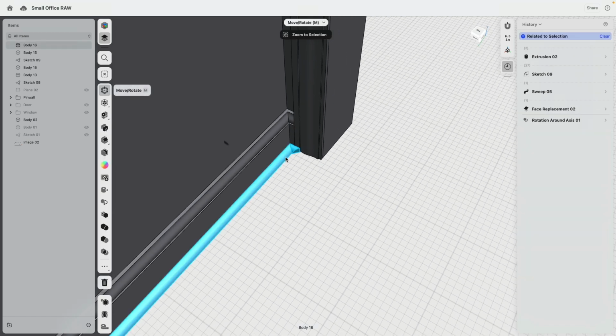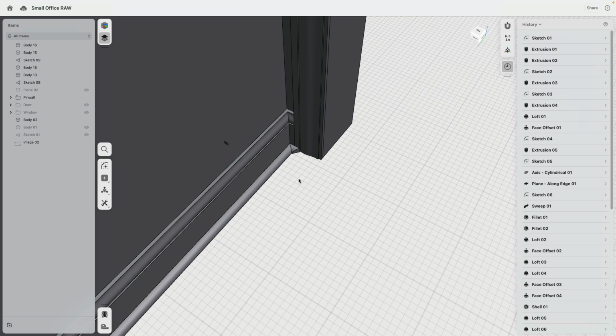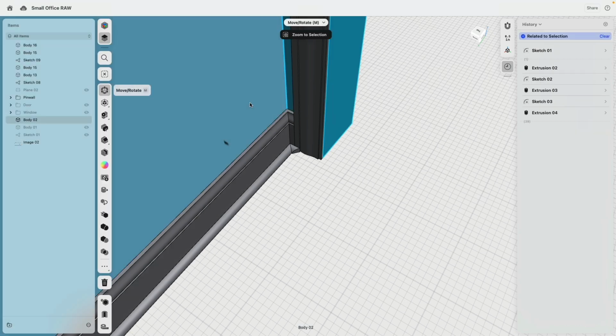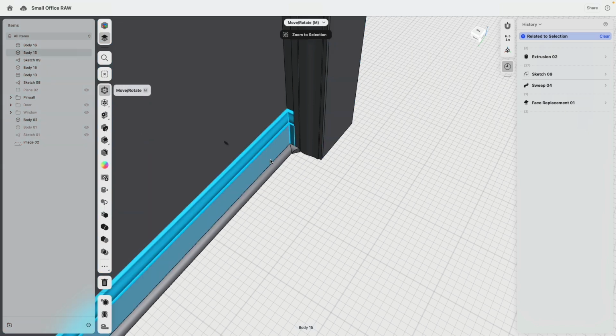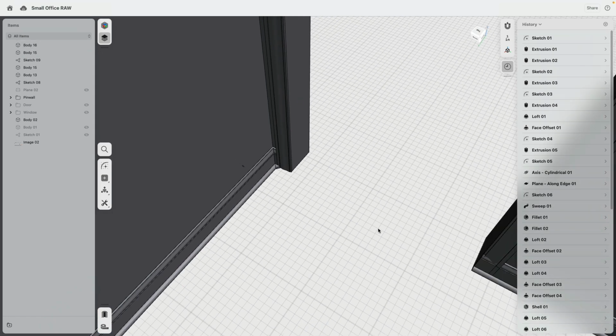By the way, why do you have actually something like this and the baseboard? If you have a hardwood floor, the hardwood floor should not touch the drywall. It might damage it. Then you have basically the baseboard that protects also the bottom part of the drywall so you don't hit it with your shoe. But between the baseboard and the wooden floor is a small gap because the wooden floor expands and shrinks in summer and winter. And to cover up that gap, that's the reason why I have that one.